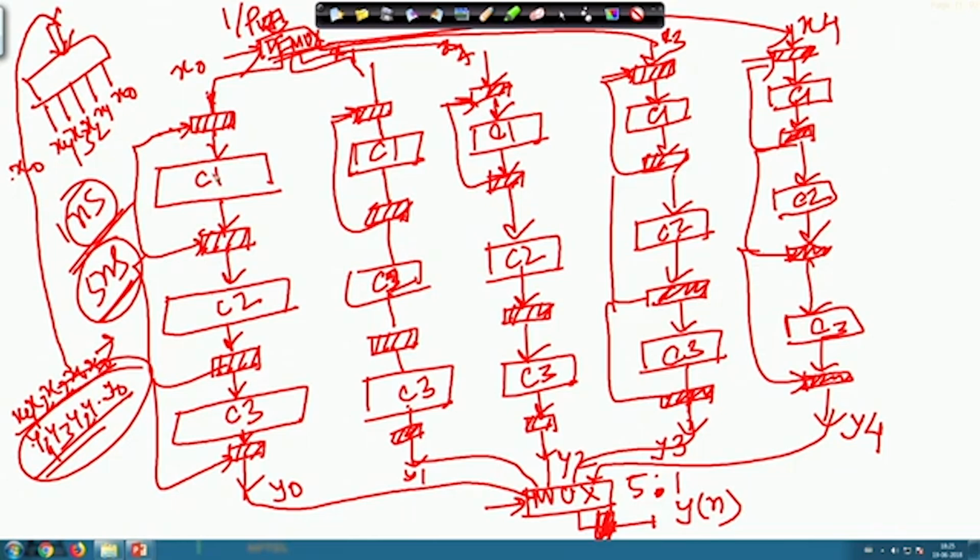At that time you see, within 3 nanosecond I have completed the job over here, but for the rest of the 2 nanosecond this block remains idle, sitting idle. At the C2 block I need 5 nanosecond for computation in each case. And again if I come down to the C3 block, it computes for 4 nanosecond, but it has to wait, sitting idle for another extra 1 nanosecond.